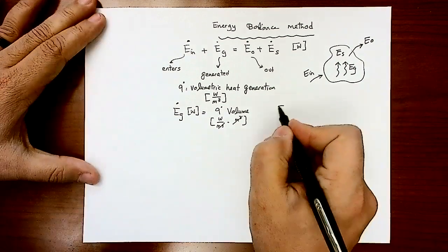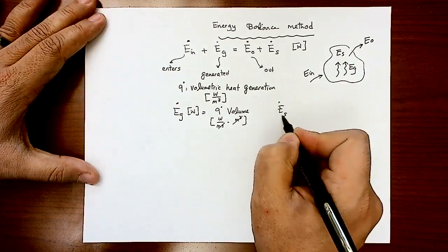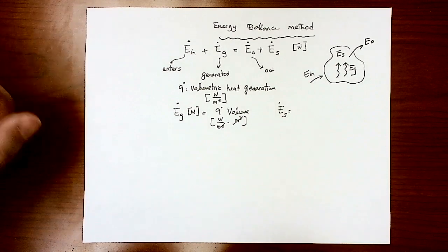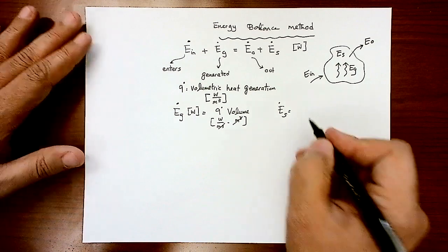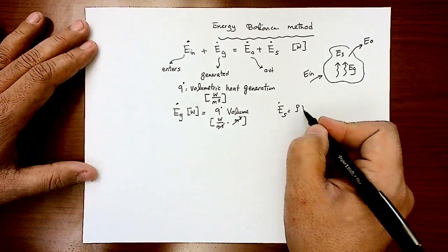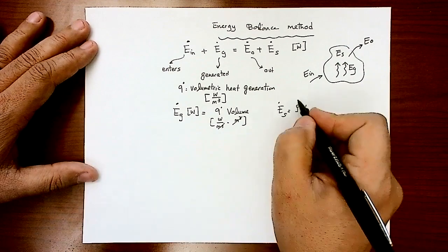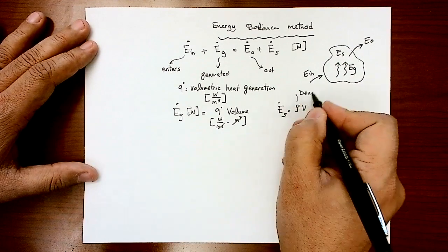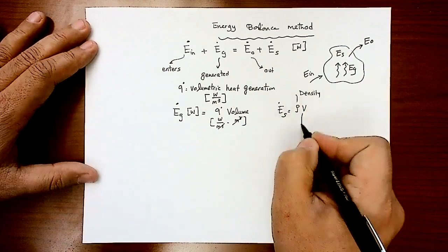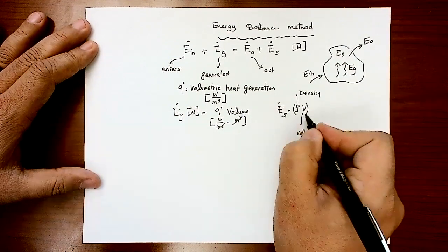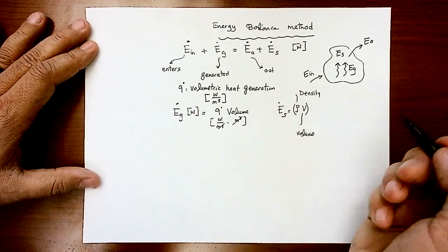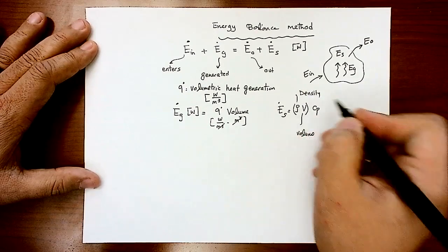Then the energy stored, if you guys recall from middle school, is equal to M C delta T. And mass can be calculated from rho, the density, times the volume. So that's the density of the body times the volume of the body. Now this completely gives you the mass. C now stands for Cp, that's the specific heat.